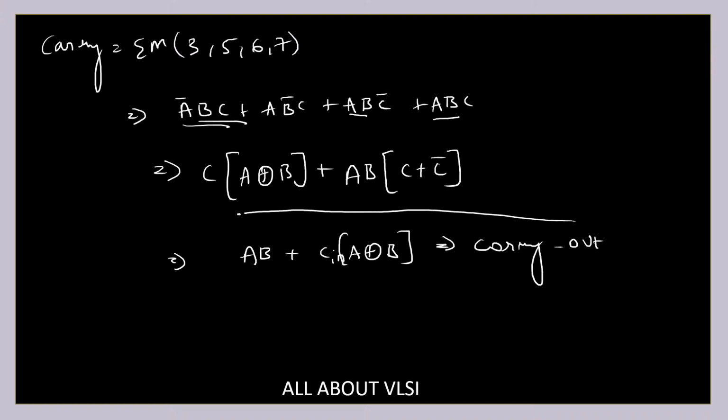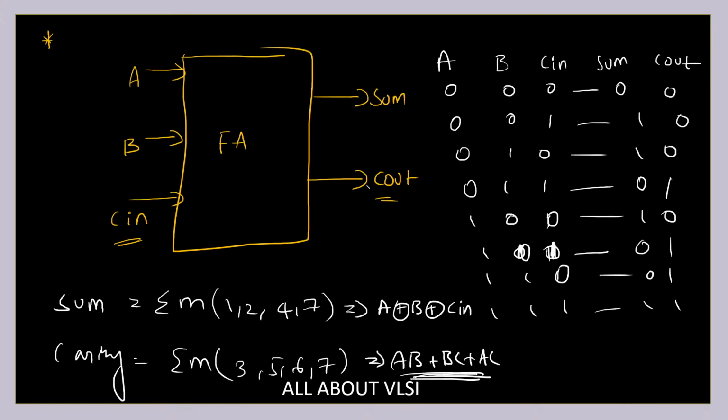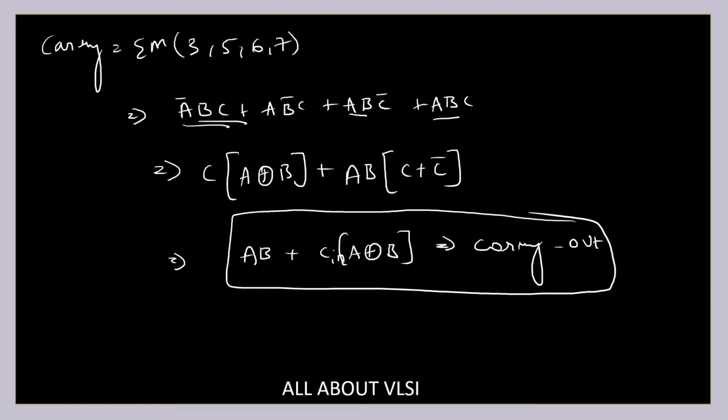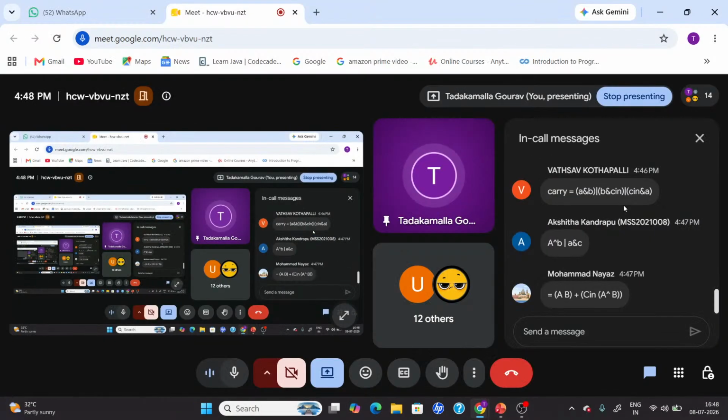Okay. So this equation we are going to use, and where we are going to use, let us discuss. Now, this is nothing but my full adder equation which I'm going to get. So full adder, can I implement it using half adder? Yeah, AB plus C into A XOR B.